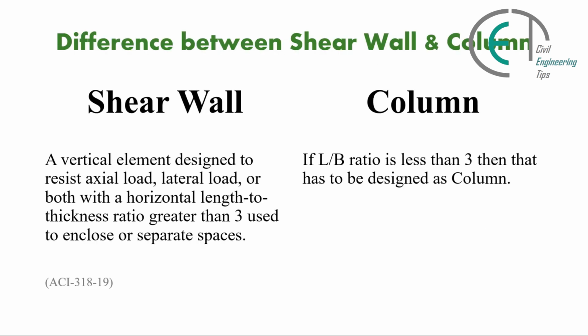Both shear wall and column are responsible for resisting the lateral forces, but there are a lot of differences between them. We have to know what the differences between shear wall and column are. Let's discuss shear wall first. A vertical element designed to resist axial load, lateral load, or both with a horizontal length to thickness ratio greater than 3 used to enclose or separate spaces.